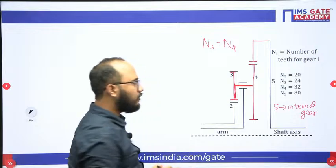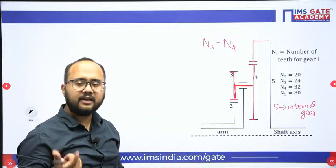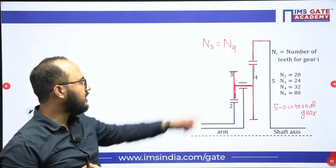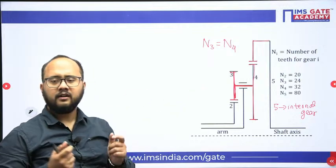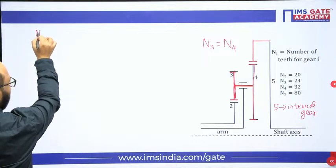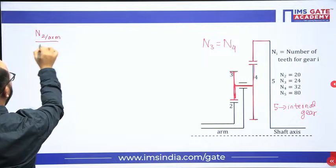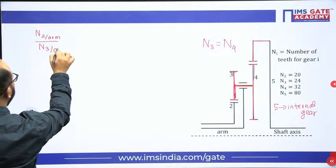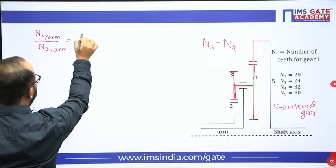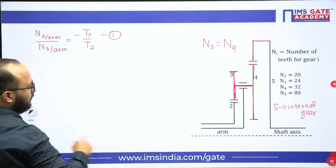N3 equals N4. Both are on the same shaft, so they will have the same speed of rotation. Then gear 3 is meshing with gear 2. According to the relative velocity method, let's suppose 2 is meshing with 3, so 2 with respect to arm divided by 3 with respect to arm will be minus T3 by T2. That is the first relation, because 2 and 3 are meshing.